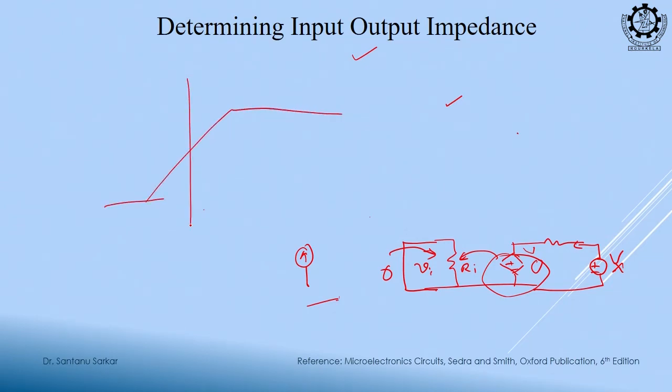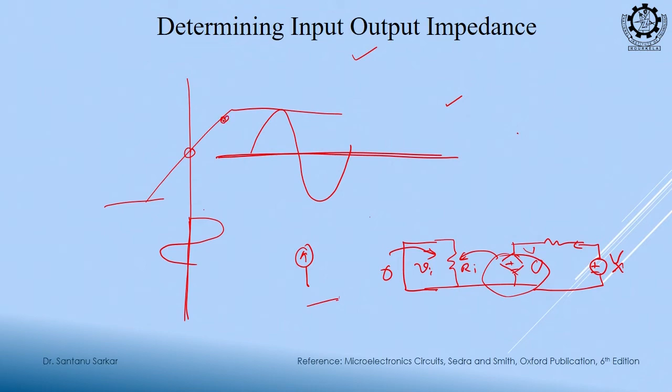This is something like this, right? If I am at the middle, I can go below and above also, right? So, if my input is changing like this, my output will change like this, but this is my DC value. So, I have a roaming position. But if I choose my Q point like this, at this position, on the upper side very little room is left, on the lower side I have full room. So, this is not suitable, the output is not amplified, it is distorted.